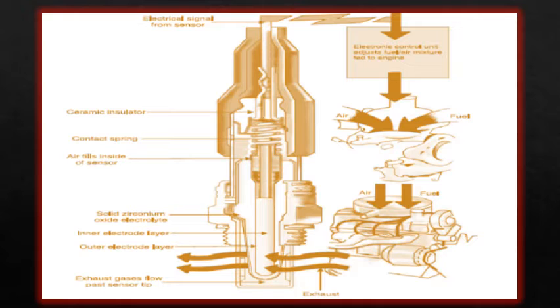If they were any higher, the engine could be subject to detonation or knocking. When this occurs, some of the mixture explodes violently before it is ignited rather than simply burning. Knocking not only wastes power but can wreck the engine. The knock sensor detects knocking as it is about to start, since impending knocking shows up as an unusual variation in crankshaft speed before audible knocking begins. If knocking is detected, the processor retards the ignition to prevent it.